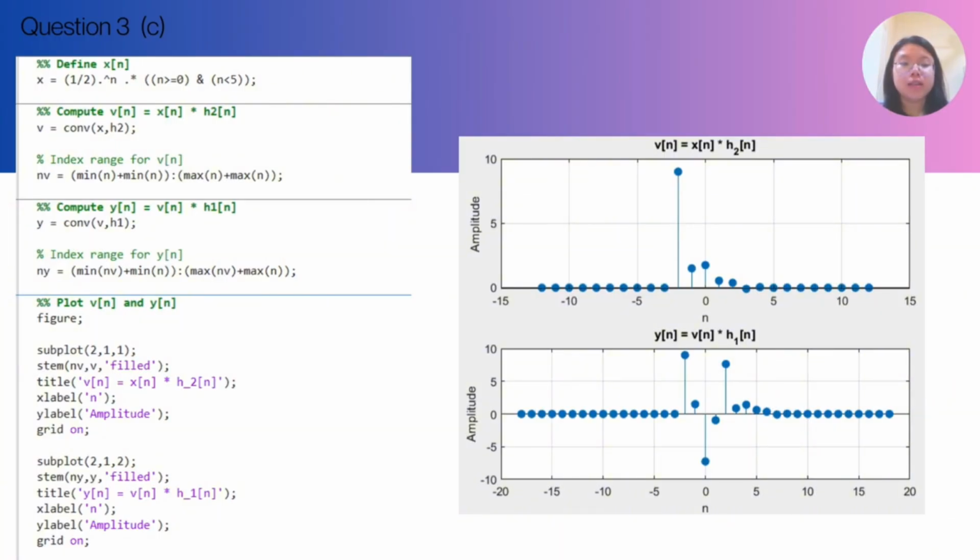However, that's of signal convolution. Here we have 2 different systems in cascade. Since convolution is associative and commutative, the overall impulse response of the cascade should be the same regardless of order. That means H total equals H1 times H2, same as H2 times H1. Therefore, theoretically both configurations should produce the same final output y[n].